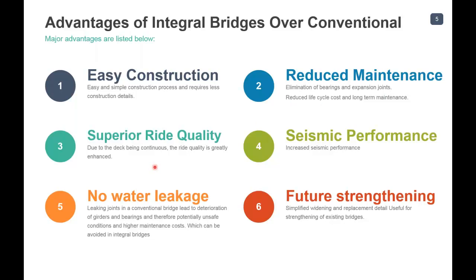You have superior ride quality due to the deck being continuous, so the rider feels great crossing the bridge. You have outstanding seismic performance, and you have no water leakage. This is also one of the main criteria, where you avoid corrosion and all those maintenance issues, because water leakage would not happen when the deck is jointless. And it's very easy to do future strengthening for existing bridges as well.